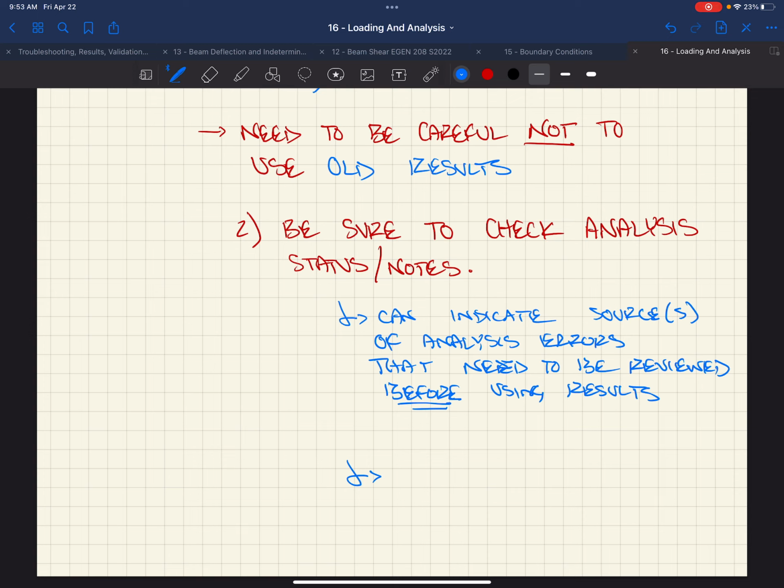But will the model run? For sure. Sometimes it might be beyond stress, maybe at like 60 KSI for a W section. It's not that far beyond yield, but the model will be inaccurate, and displacements might seem okay. And the little color code might be yellow. It's like, hey, I don't know, you're the designer, not me. Just saying, it's beyond yield, and you can use those results.